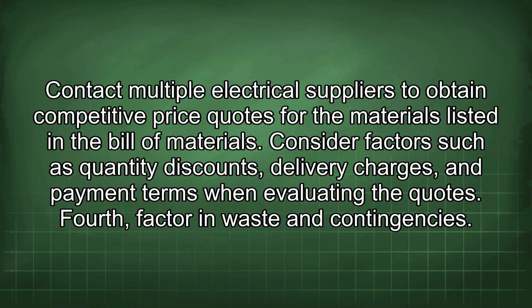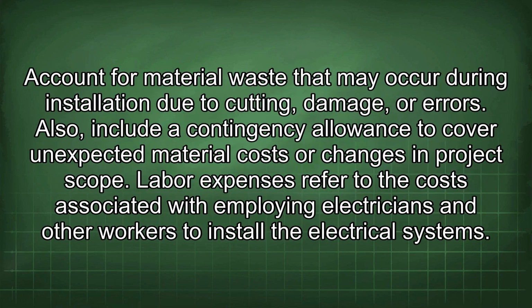Fourth, factor in waste and contingencies. Account for material waste that may occur during installation due to cutting, damage, or errors. Also, include a contingency allowance to cover unexpected material costs or changes in project scope.